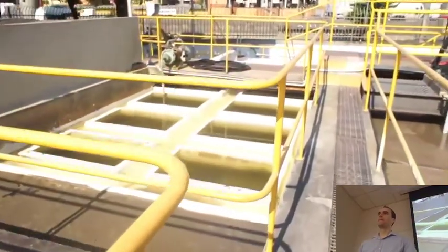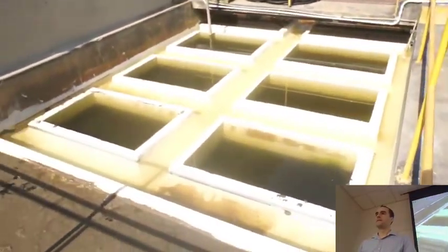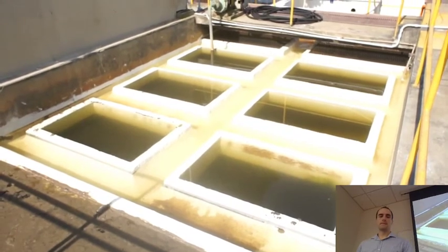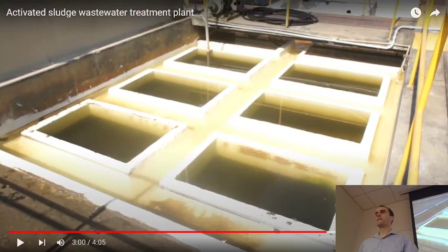So is that where you kind of do the denitrification of nitrogen and phosphorus and stuff? Does that happen in the secondary treatment or is that something else? Okay, so it's a great question about denitrification, whether that happens in the secondary treatment step. A lot of those, there will be some if the conditions allow, and not all treatment plants are built the same. Sometimes you might have an anaerobic process first, which will set up the biochemistry and the chemistry a little differently, and then you have aeration. Sometimes you'll go aeration, then aerobic.